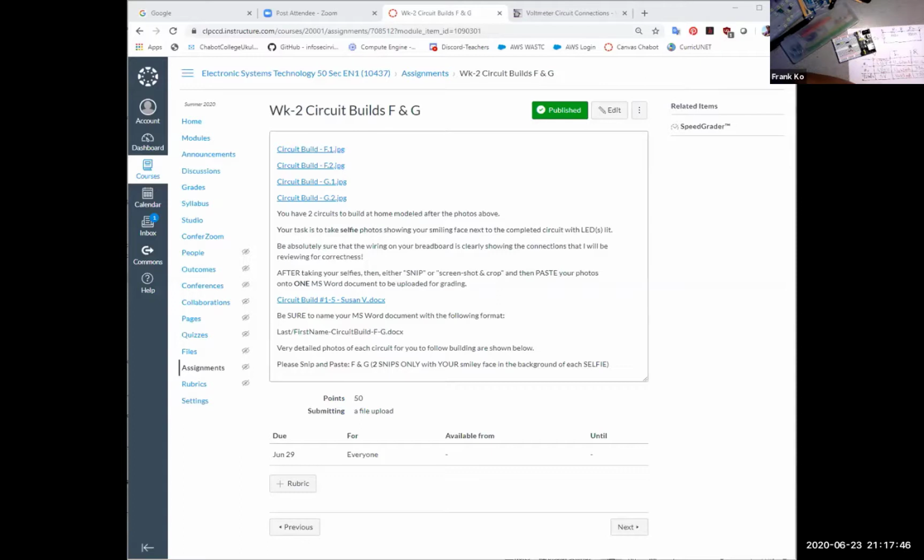I've built this exactly the same way. Red power rail jumps to the first resistor, with a jumper to the second resistor, to the upper right-hand pin of your switch. The lower left-hand pin of the switch goes to a jumper wire, and then to the LED, to another jumper wire to go back to the source.